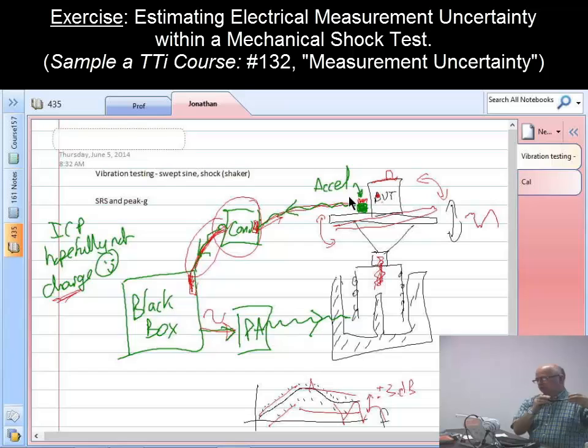I'm assuming that the platform is rigid, and typically the manufacturers, going up to 2 kilohertz with these big guys, there's not very much plate resonance to mess us up. There can be some. I think you mentioned resonances like that. But we can almost assume rigid body, and so we can get an estimate of that. At that stage, we can say, okay, in that frequency range for that particular device under test, we know we've got so much rotation going on.